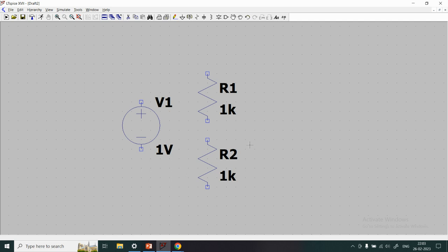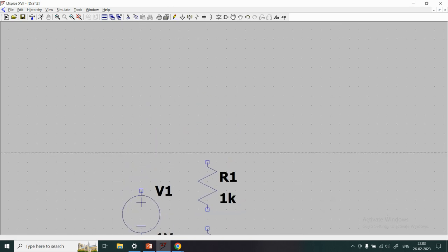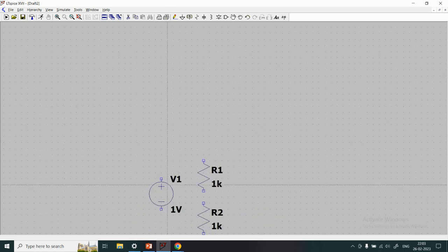Once I have the circuit complete, I will click this symbol, that is ground. So I click here on ground, for example, right here. Again I press Escape, and then I need wires. So I go here and click this symbol. There are wires. They are used to make the electrical connection. So I click here and I come to the screen.